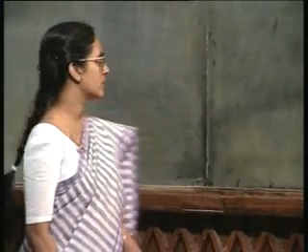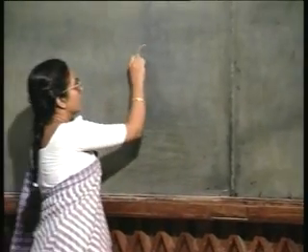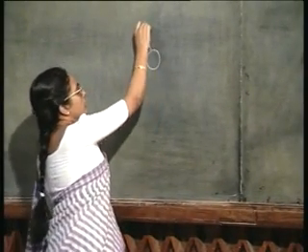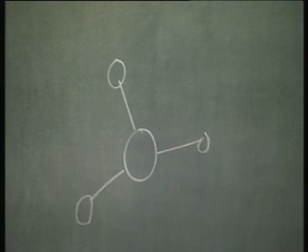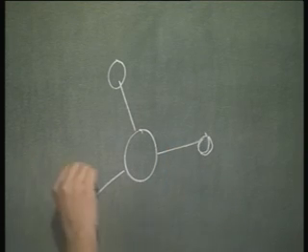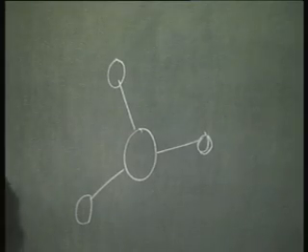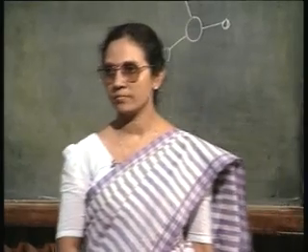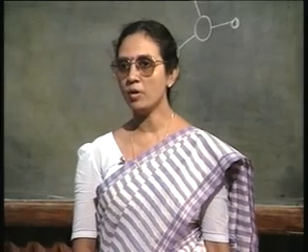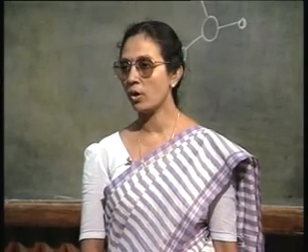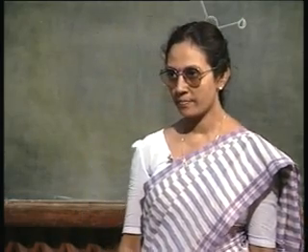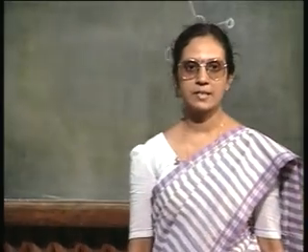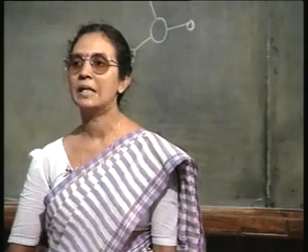Normally, inside this diamond structure, we have discussed that each atom is bonded to its 4 nearest neighbors in a tetrahedral structure, right. 1, 2, 3 and the 4th one going inside the board, but not so on the surface. On the surface, some of these bonds are not present. We call these dangling bonds. These bonds are dangling in space. So, any real crystal is far from ideal.